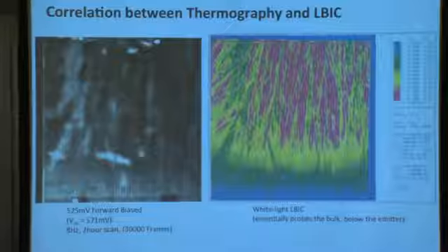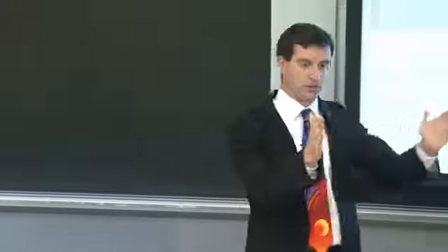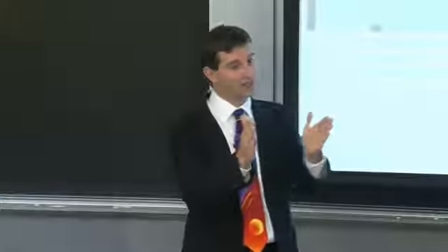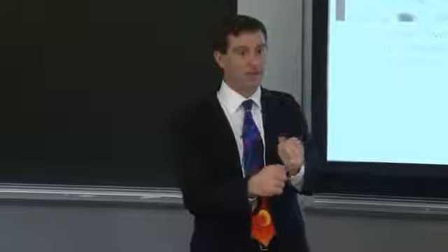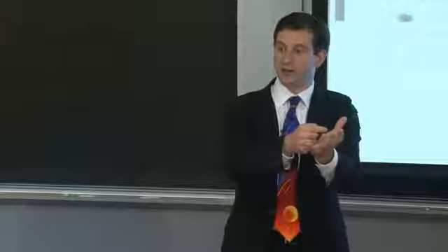Once again, the explanation: if you have a large forward bias condition, the barrier is lower, and carriers can easily diffuse into the bulk. The carriers diffusing into the bulk will go a certain distance before recombining. If the diffusion length is short, they'll recombine quickly, which means now there's no more carrier, which means that the diffusion current will push another carrier into that spot, right?